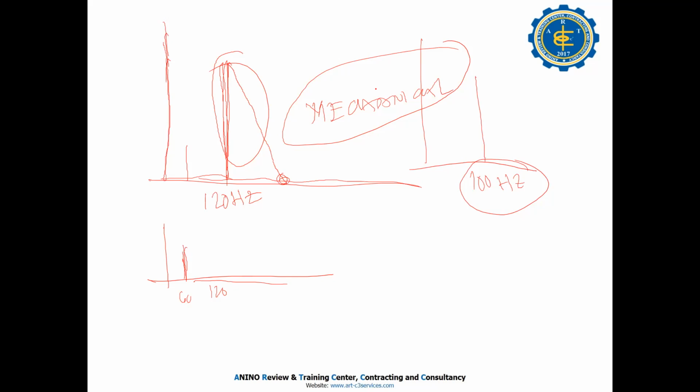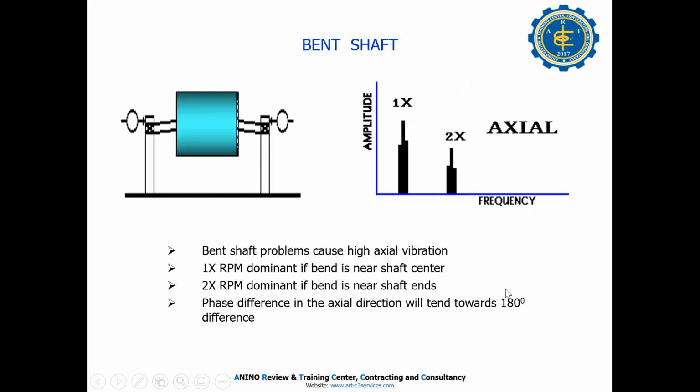Stop: when the vibration is gone directly, it is an electrical problem. Then another: I start, then stop, and the vibration slowly goes down, so it is a mechanical problem, misalignment. That's the technique for two times line frequency. So you're lucky in your country, you have 50 hertz line frequency.